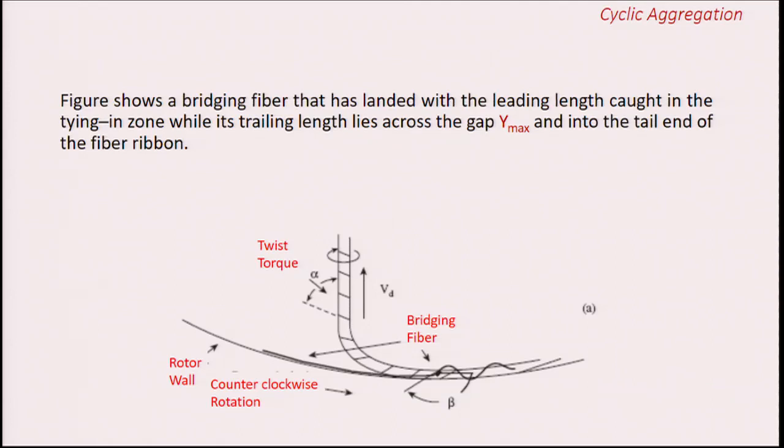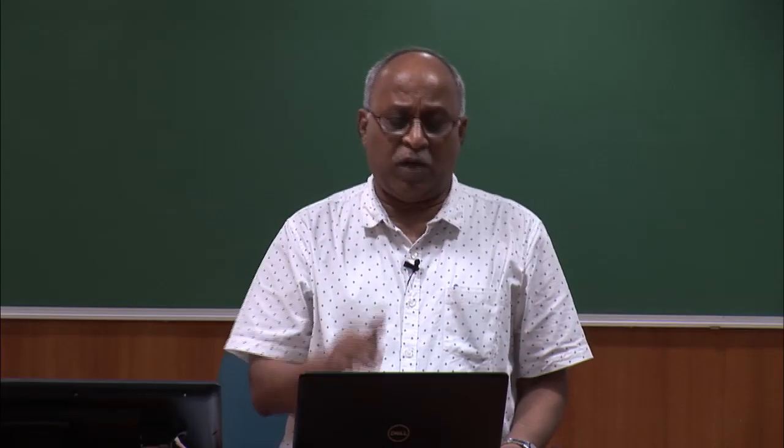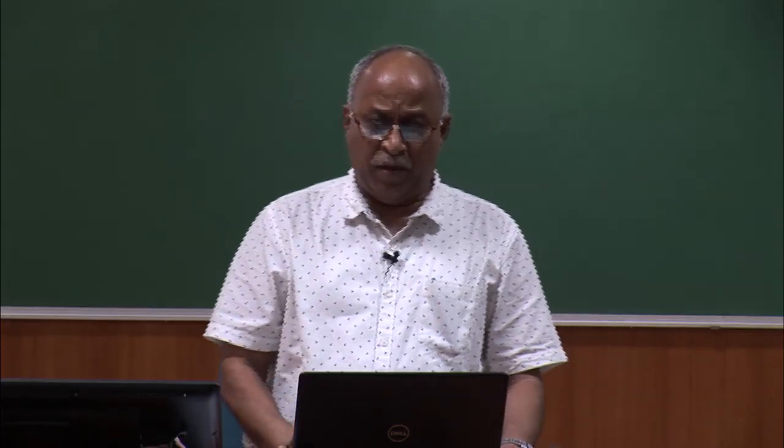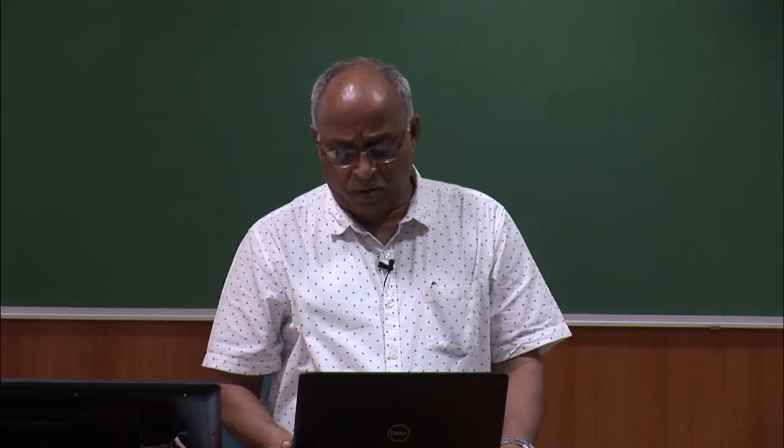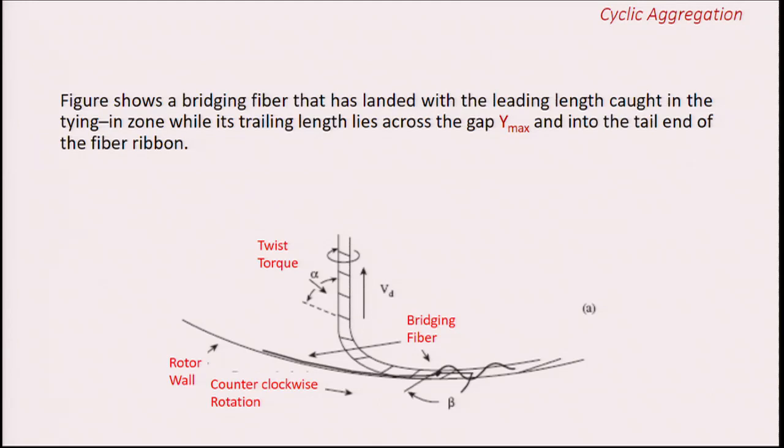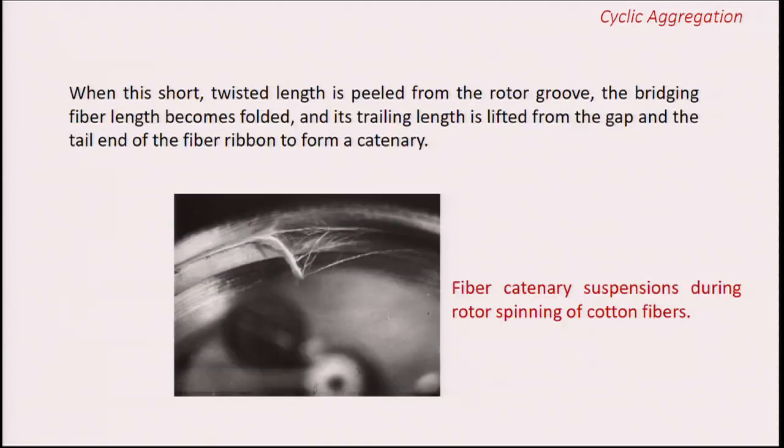Accordingly it will have the same twist. If the yarn is S twist, it may have S twist, or if it is coming from the opposite direction, it may form a Z twist also. So, the wrapper fibers can be S or Z twisted when the core is S twisted. So, the direction can change.